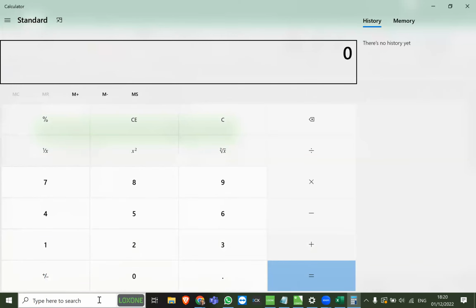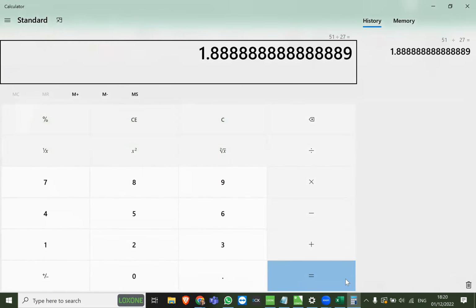Now, you can do a very simple calculation. Let's say that one of your DIN rails can fit 27 breaker units worth of devices. So you can say 51 divided by 27, which is going to give you 1.8. So 2 DIN rails are going to be enough in a bigger panel. However, if we start thinking about terminal blocks and maybe a little bit of heat dissipation, you can start seeing where you can add a second rail or maybe a few terminal blocks. And if you want to have the power supply and backup on its own rail and nothing nearby on the left or the right-hand side, maybe we're talking about 4 DIN rails.